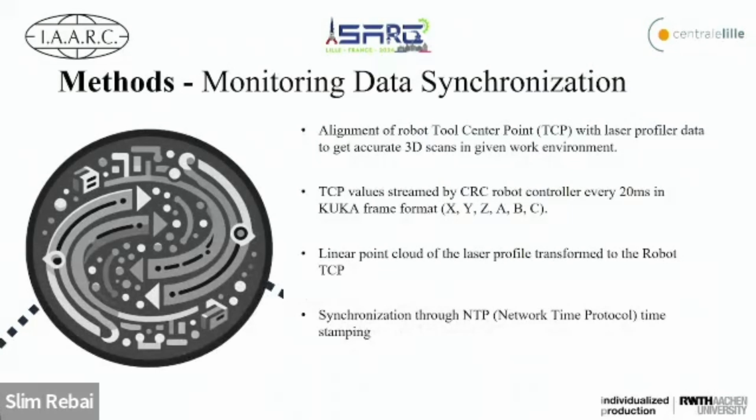For that reason, the next step of this modularity is a service. So we had an actuator, we had a sensor, and now we have to make sense of it in 3D space. For that, we used a standalone, Dockerized, containerized service, which takes the transformation data and sensorial data and combines them in 3D space so that we can make sense of this three-dimensional data and save it iteratively to be able to get a 3D point cloud from a single line scanner sensor.